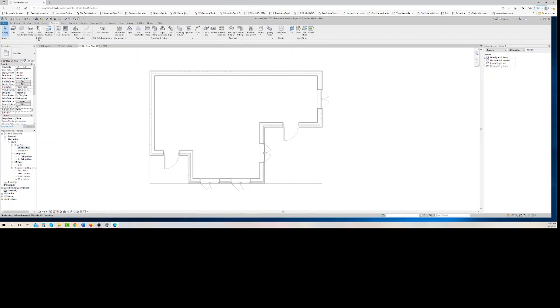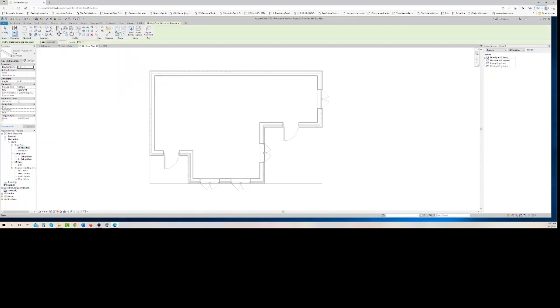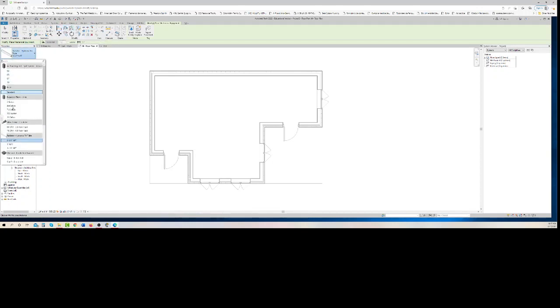And the first thing that you do when you put HVAC in is put in some mechanical equipment. It's things like hot water heaters and chillers and filters and air handling units. So there we go. We're going to put the air handling unit in. And so when you click on the system's mechanical, this comes up and there's a lot of stuff already loaded for you. And so we're just going to pick this smallest one.